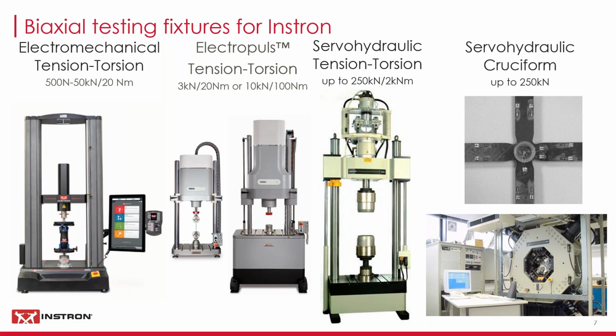Biaxial testing. So this question specifically mentioned fixtures. Really, I think biaxial testing is more a question of actually the machine. We have a range of biaxial testing machines, from electromechanical static machines capable of forces up to 50 kilonewtons, 20 Newton meter torque, probably more targeted at component and device testing than actual materials testing.